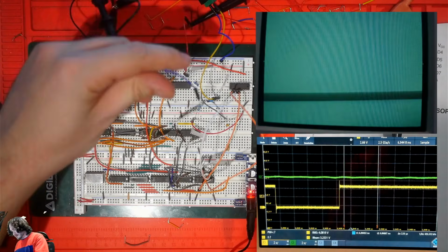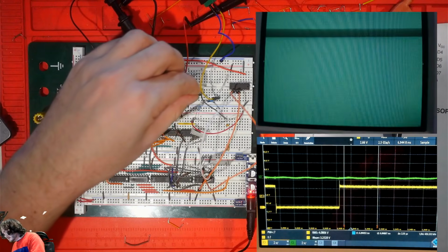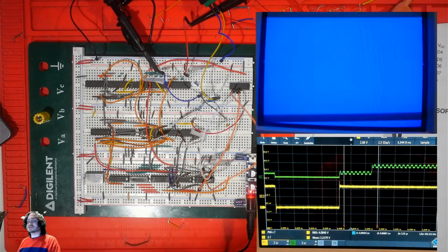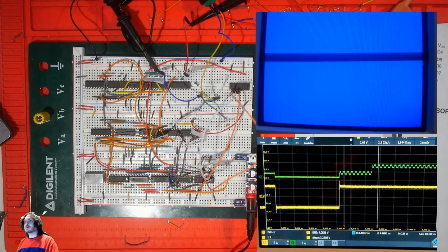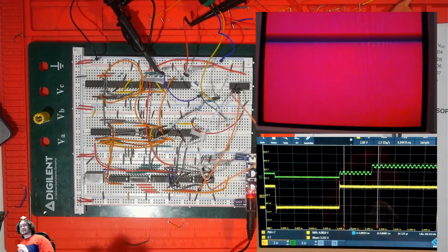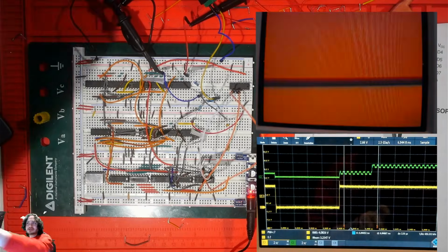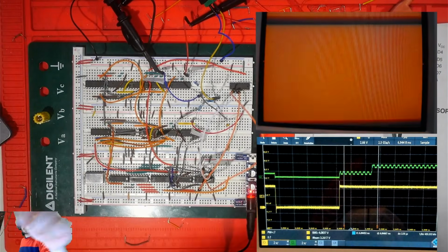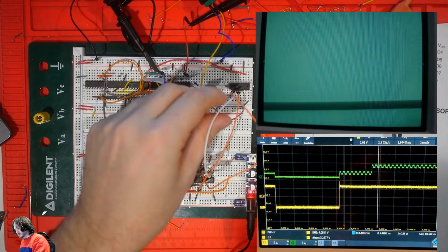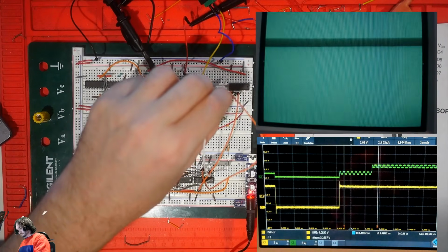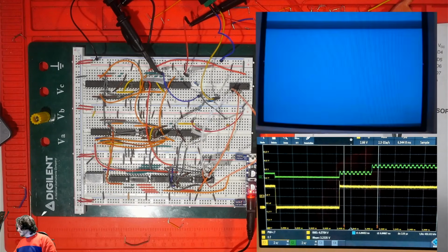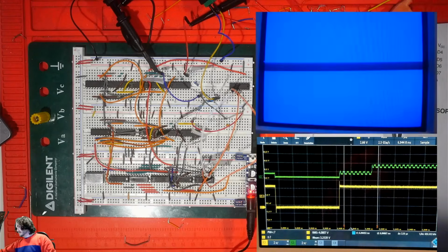We get the oscilloscope back onto the video output. So now you can actually see, as the color changes, we've got our wiggle of the color carrier. And unlike what you might expect from seeing up and down on here, we're not getting vertical stripes like we do for, if I plug this into luminosity. Where's my wire?